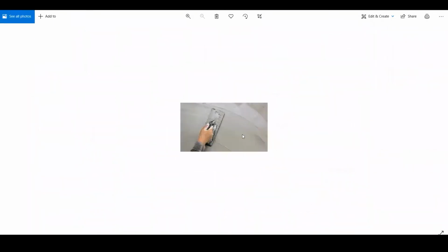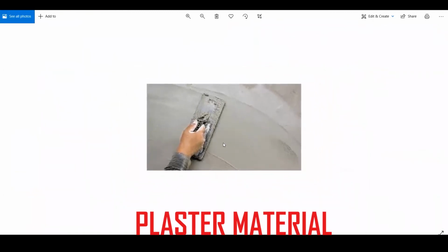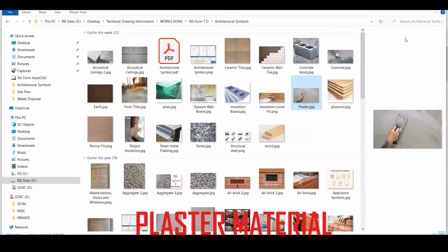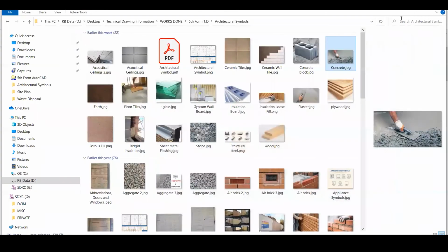Right here. This is a guy here smoothing a wall and applying plaster onto the wall. So after we have finished placing the concrete down, then we need to smoothen it. So some people come back and add a layer of plaster, which is the same concrete, a thin layer, and just smoothing it down so that the wall is smooth and you won't see all the imperfections or the cracks, or any unevenness of the material. The reason for applying plaster is it's used to receive the paint.